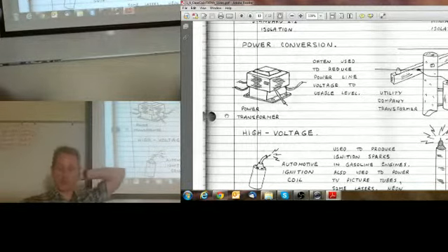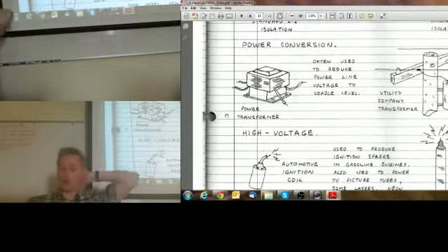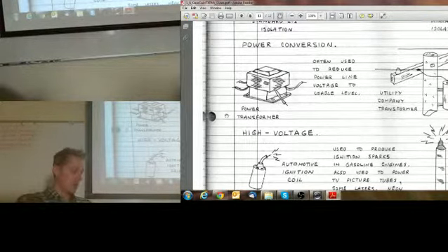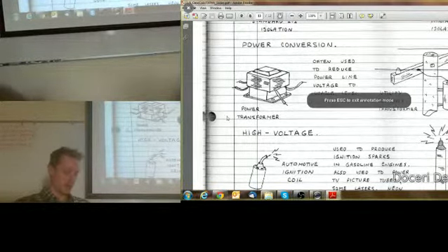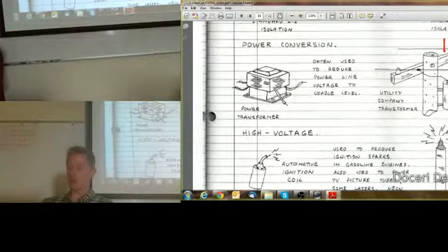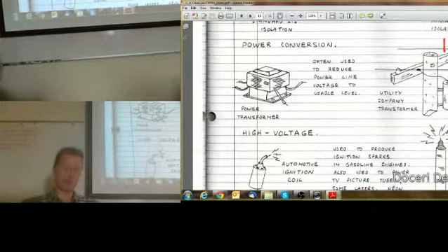And so we have thousands of volts on the main lines, but when it comes into our house, I don't really know what the voltage here is, it's tens of thousands or something. But when we step it down, we usually have a center tap, we have 240 across these, but if you use a center tap, then you can get 120 and 120, 180 degrees out of phase.